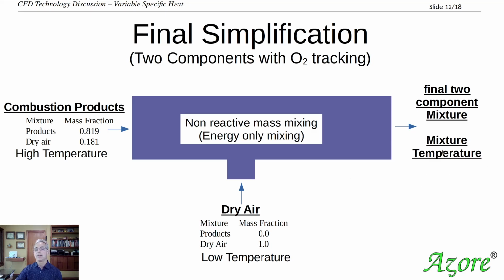And then that allows us to not only calculate our equivalent mixture temperature, but it will also allow us to have a representation of the amount of air and oxygen that you might have, as well as maybe the distribution in that mixing process right here. So once again, we have reduced this problem from a 5-component system where we had trace 4 scalar fields to a 2-component system.